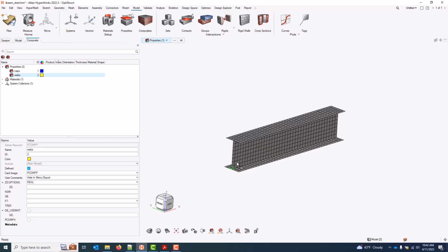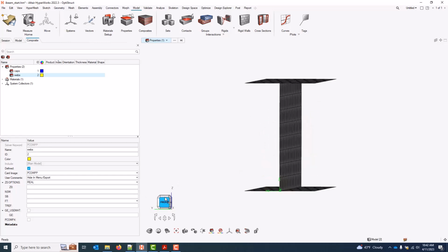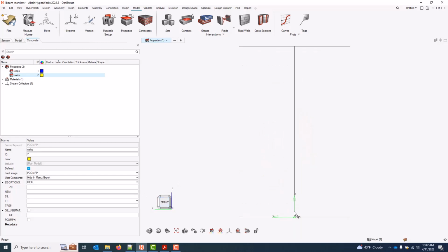For the purposes of this example, and typically a convenient way to define these T-junctions, is to have the elements located such that the web elements are at the midplane of the laminate and the caps are at the tooling geometry. At the midplane, it's essentially arbitrary which way they stack, as long as we take care of our bookkeeping, which we'll do at a later point.